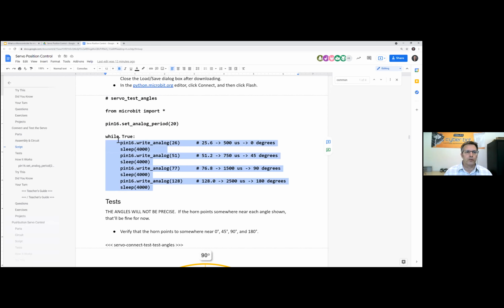Since we had one report, I'm definitely concerned that once this gets out into the world, we'll have more than just one report. I think there are process variations within the digital servo, so that unfortunately 26 is sometimes really 25 to the digital servo. The oscillator on the Microbit is pretty precise in comparison. I think what's happening is the oscillator or resonator in the digital servo that it uses for its clock to compare with the signals the Microbit is sending is more prone to temperature and process variation.